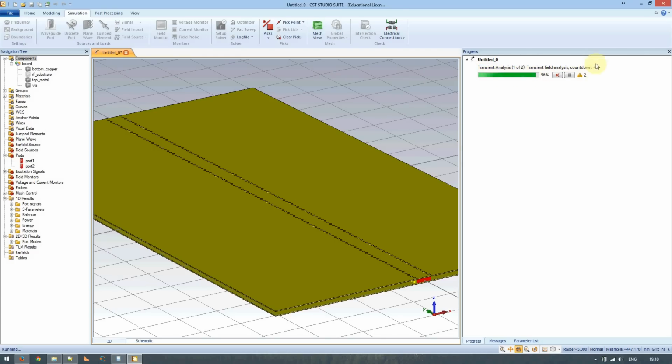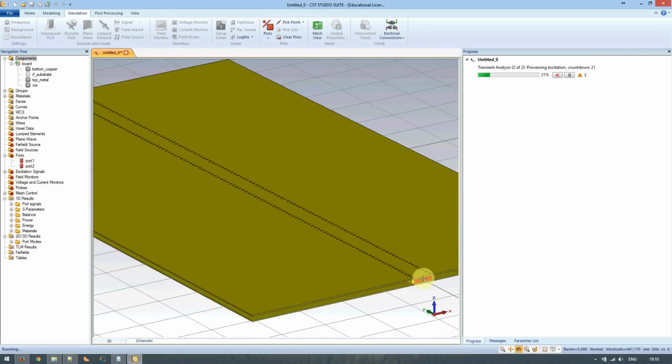The one exception, in which case the transient solver will struggle, and you will see huge numbers here, is if you are simulating over a cutoff frequency and the energy starts to bounce back and forward. What the transient solver does, and it's useful at this point if you understand a little bit of computational EM, I found that even just the limited knowledge that I had, a little bit of reading that I did, helped me to understand what CST was doing.